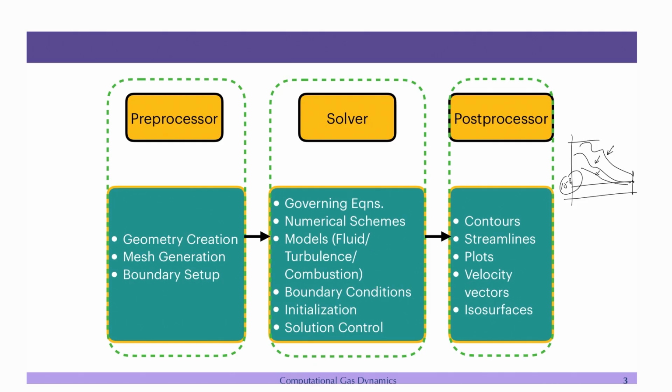Is it making sense? Okay. For example, if you have a flow around an aerofoil, there will be a stagnation point here, and so how will the pressure look like? Are you getting this profile on the blade? So, first of all, to see whether the flow is making sense, where the velocity should be accelerating, whether it is accelerating, are the streamlines okay.